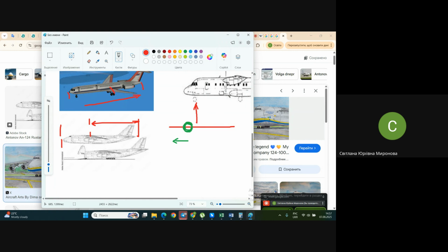In case you place these engines to the back, somewhere closer to the fuselage to make a more comfortable life for your passengers, for instance, closer to the aft fuselage, what happens here? The wing together with the center of gravity travels closer to the middle of the fuselage, maybe even farther than the middle of the fuselage.